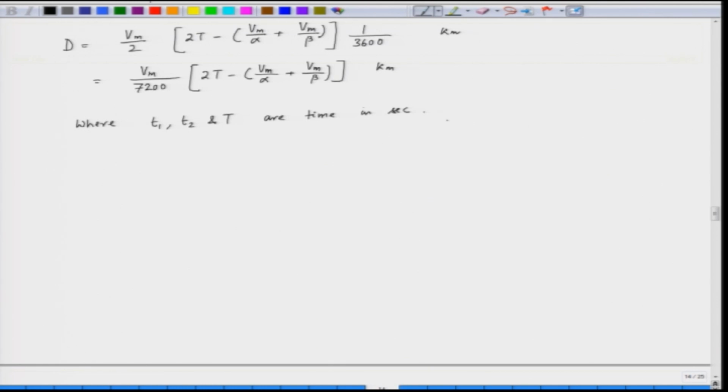Now, we have to find out the drive rating, and for that we also have to find out the tractive effort. When the train is moving, what are the various components of tractive effort? In the steady state, that is train resistance. In the steady state, we have frictional force: internal friction, external friction and the wind friction.